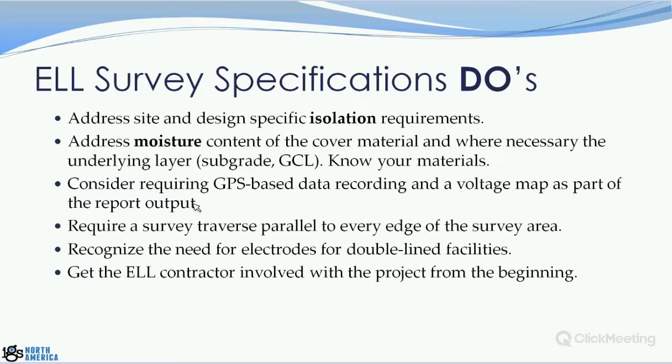Address moisture content of the cover material and, where necessary, the underlying layer. So usually subgrade is fine. If you have GCL encapsulated between 2 geomembranes, then you absolutely need to be aware of the moisture content requirements.